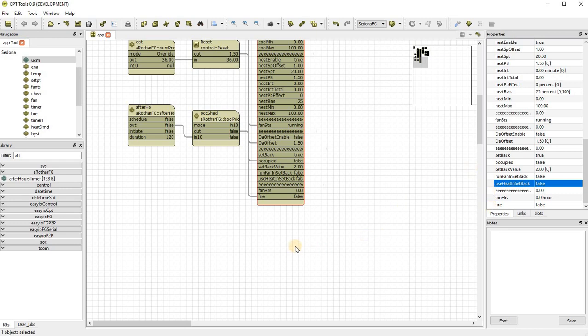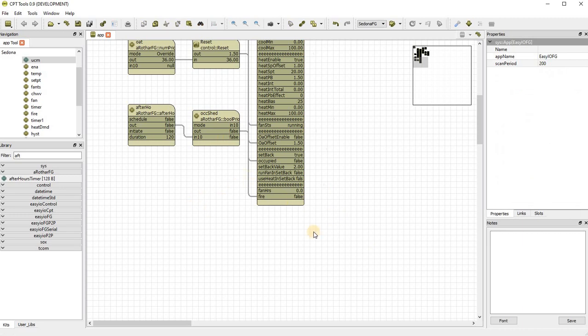If it doesn't get cool enough to freeze things, you might want to exclude heating as part of your setback strategy, and that can be managed here. You may wish to include it during a calendar period and exclude it outside of a calendar period. So again, you can link varying things to this setback control to give you the desired outcome all in the one block.